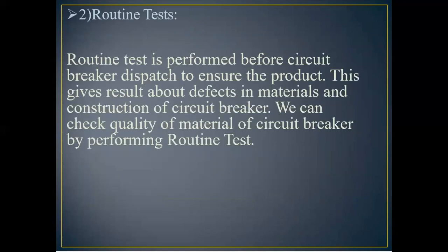Then routine test. Routine test is to be performed before circuit breaker dispatch to ensure the product. This gives results about defects in materials and construction of the circuit breaker. We can check quality of material of the circuit breaker by performing routine test.